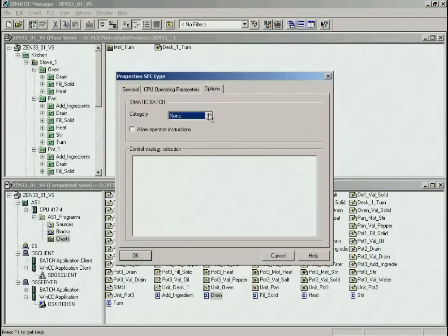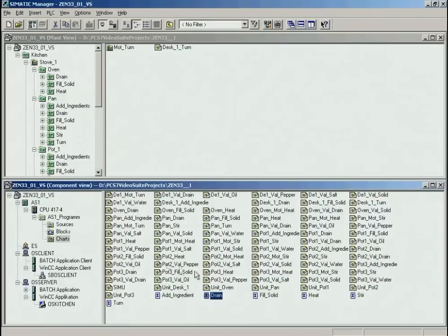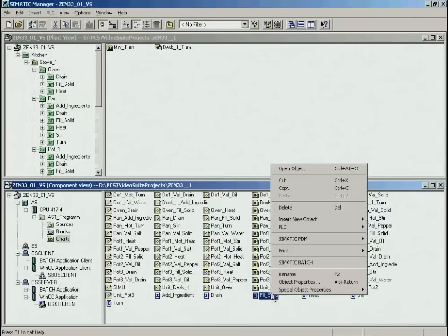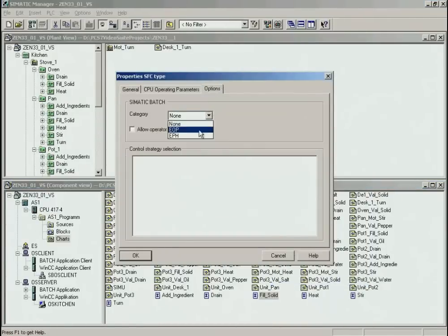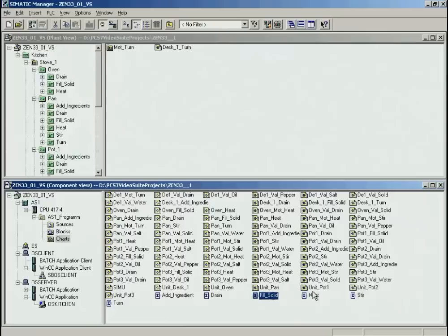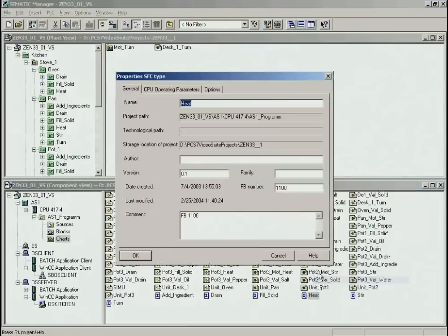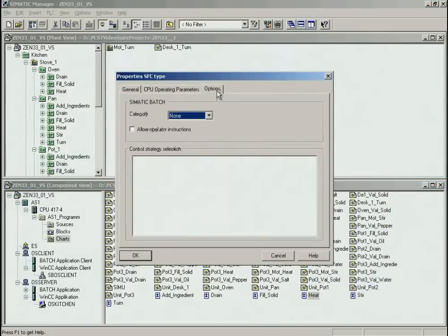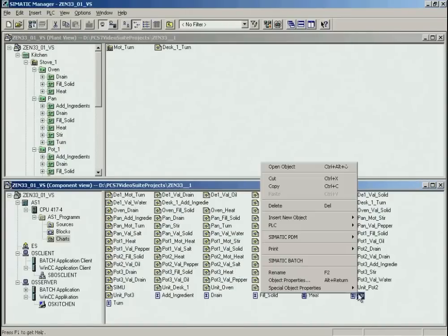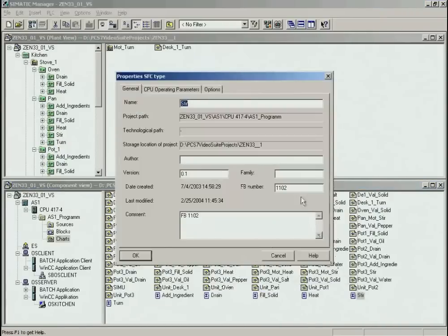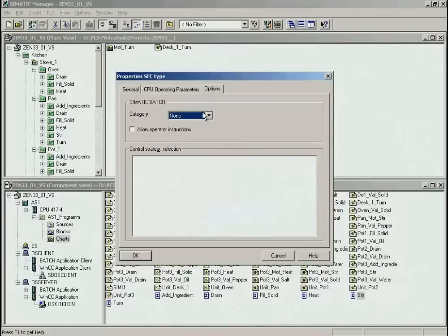The difference between the two is that an EOP is linked to a recipe operation in hierarchical recipes, and an EPH is linked to a recipe phase. In general, the scope of an EOP is more extensive and more complex than an EPH. Creating recipes using EPHs allows greater flexibility. EOPs are useful when the equipment functionality is fixed.